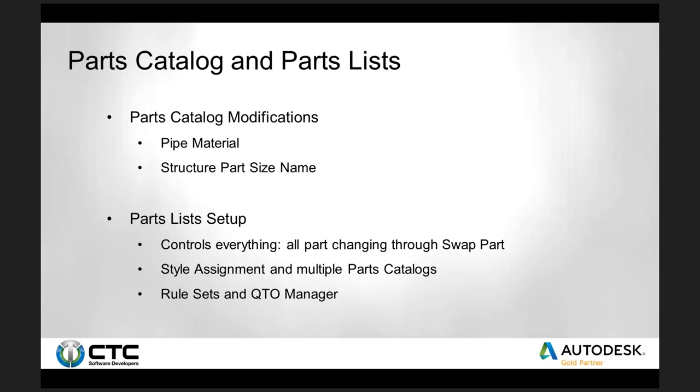An existing sanitary you want to tie into. Okay. In order to have that be controlled through the parts list, we need to be able to swap a part. Well, if you want it the same size as perhaps its proposed structure counterpart, you can't have two sizes in the parts list under the same family. Okay. So what it means is you make duplicate catalogs.